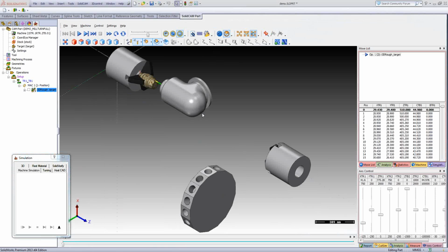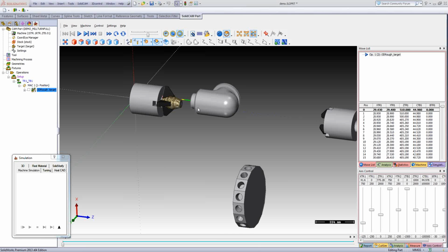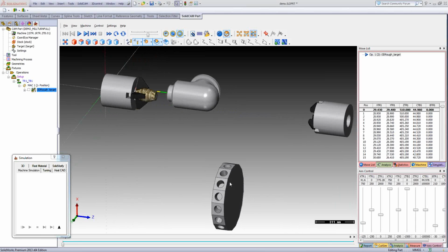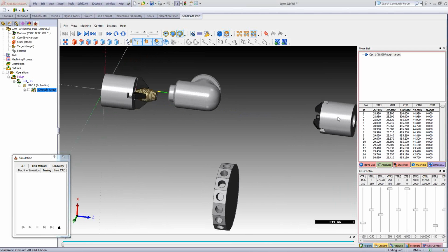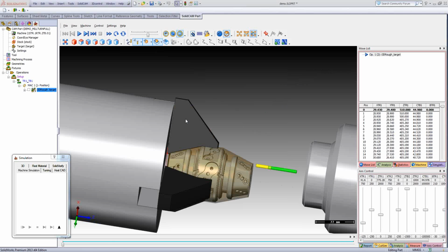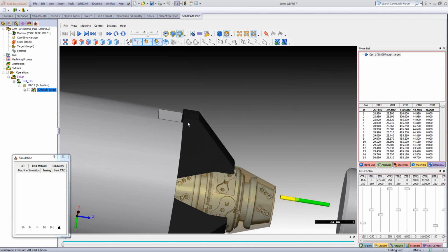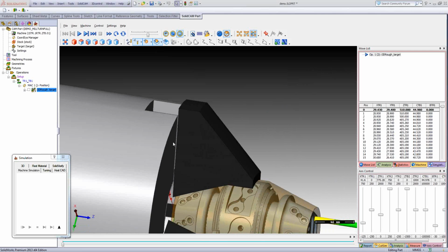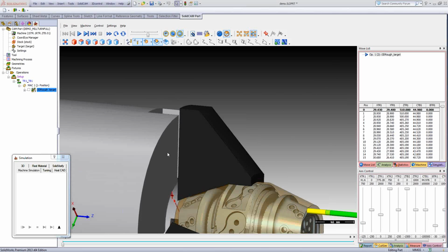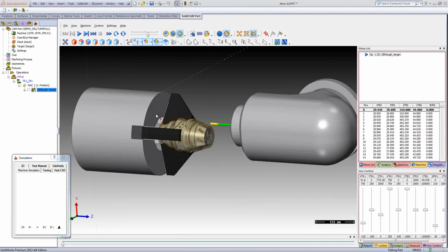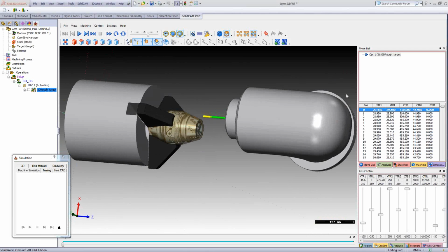Okay, I have a schematic machine only with B-axis upper turret and rotary for lower turret, main spindle and back spindle. You see, because of the setup I defined, 165 millimeters, Mach 1 from the face of the spindle. That means the fixture will be connected here on the face of the main spindle. And let's play.